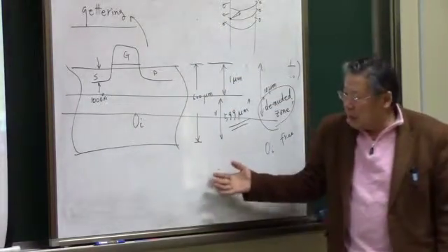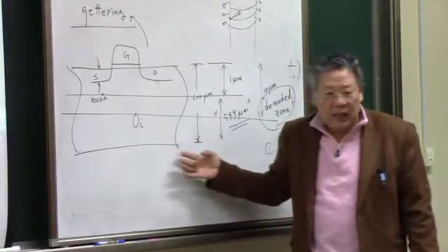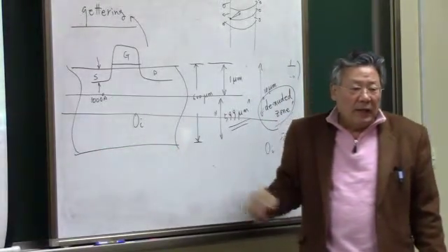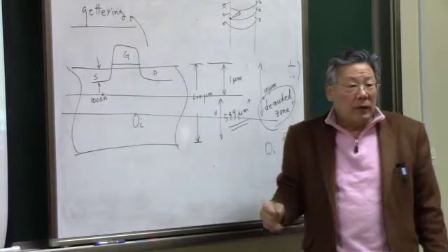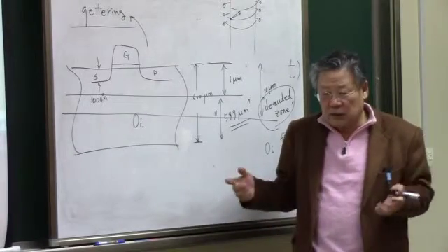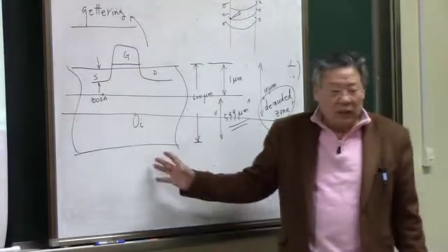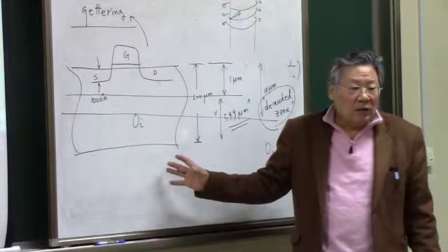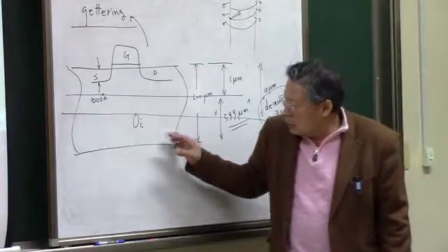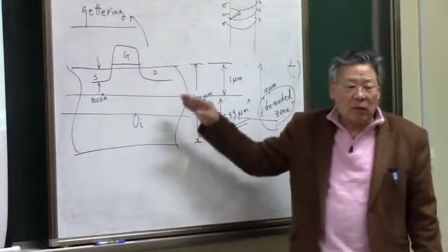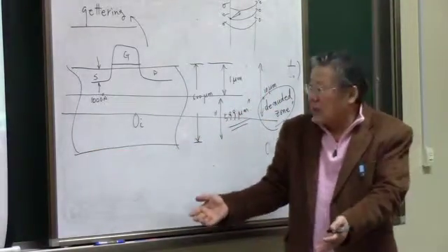Or we can damage the back side of the wafer with sandpaper, and we're going to discuss the ion implantation later, but using ion implantation of argons and so forth, we damage the back side of the wafer and then put it in the heat cycle.